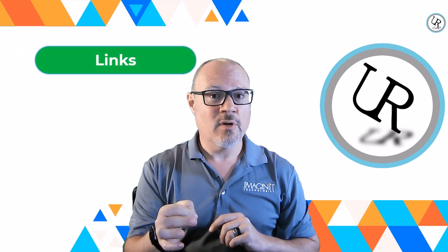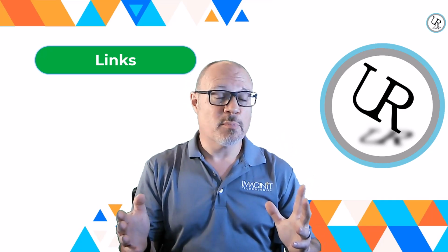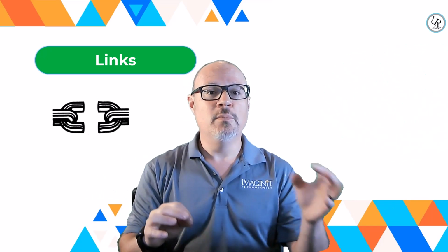Today we'll be talking about creating links, which are very important in the Revit software for various reasons. If you're working with multiple disciplines, multiple parts of the project, different companies, all of those files are typically used in separate locations and they have to be brought together to make the project whole.